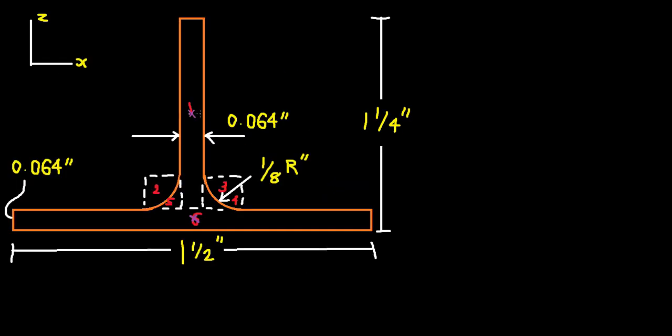So for this shape, we already know our total height for the entire figure and its length. We calculated its length by subtracting 1 1/4 minus 0.064. So if we subtract both of those, we get the length of this entire first shape. Now in order to get its centroid, we simply divide it by 2. Now, since we're basing it upon the x-axis, which is our horizontal axis, we must include our 0.064.